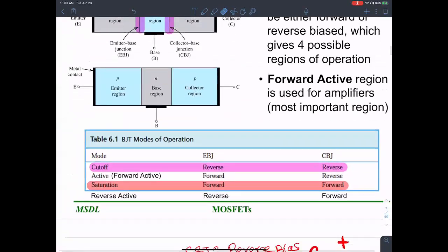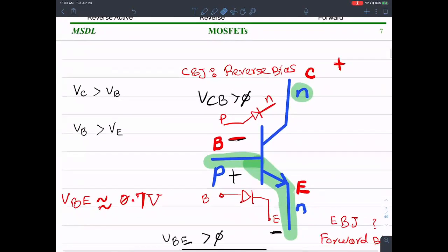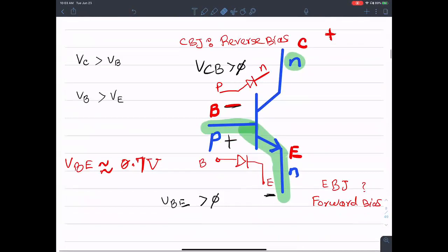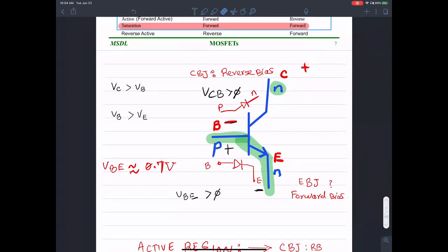Okay, we talked about this. And in addition, I mentioned the symbol. I talked about the symbol of the BJT in NPN, with the arrow not pointing in. That is NPN. And I mentioned that for NPN, we like to draw the collector up on the north, the base in between, and at the bottom, south, is the emitter.